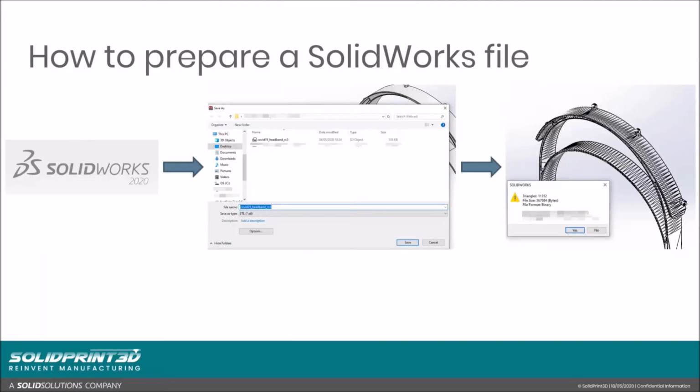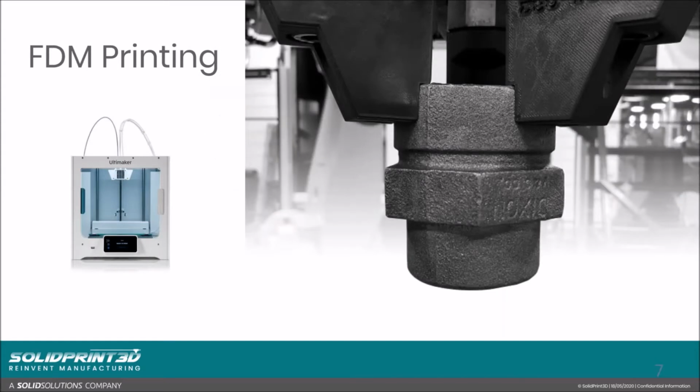Starting off with the old SolidWorks slide. So firstly, what we're going to have to do for most of these processes is get a hold of the file type, which is going to be an STL, or in most likely cases, also 3MF files as well. So your STL you can get out of SolidWorks pretty easily. File, save as type to STL, and you can see it turns it into thousands of different triangles, which is then readable by the middle ground, the slicing software that's used for the printers. So that's kind of the basics of getting a hold of the file.